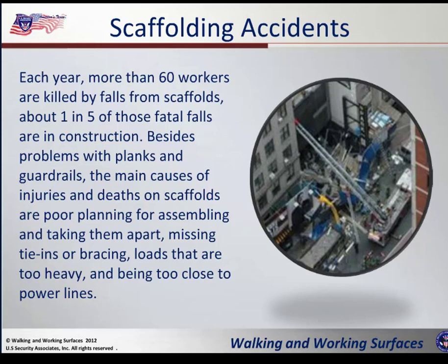Now, again, you're not going to be responsible for putting scaffolds up, but you can take a look at the scaffold, just to make sure that it's assembled properly, that people are using the proper precautions when they're putting them together and taking them apart. You can check and see if they have any tie-ins missing, any braces missing, or if what they've got on that scaffold is just too heavy, or maybe it's close to a power line.